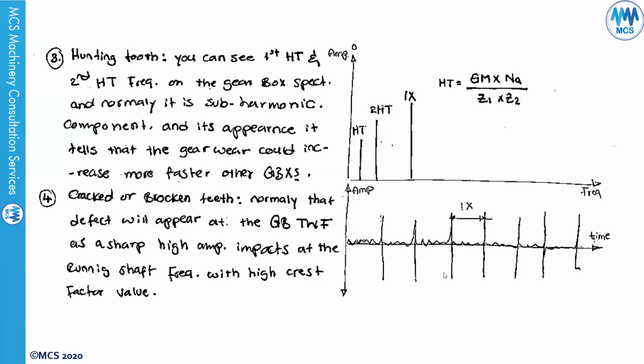Cracked or broken teeth, you will see impacts on the time waveform. The time waveform is essential in the analysis of gearboxes. And when you see impacts on the time waveform, this will be a very good indication of cracked or broken teeth.